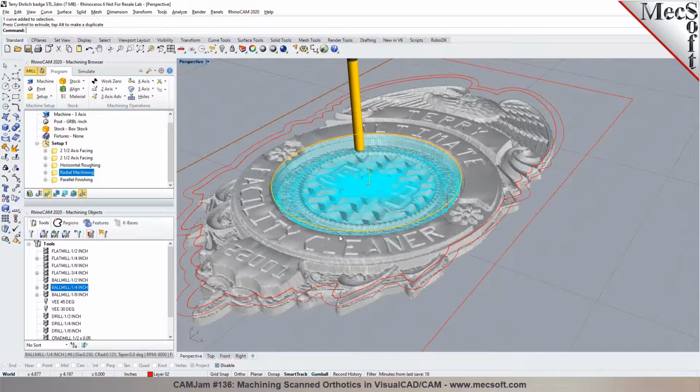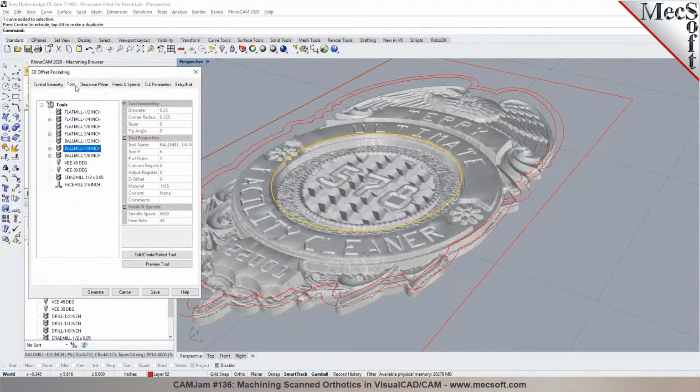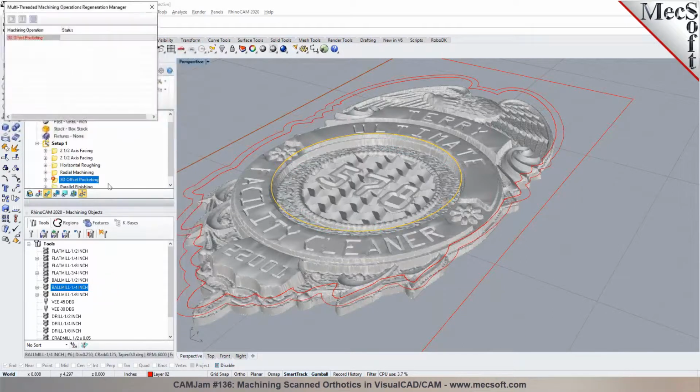With the Pro, we have more advanced 3D methods, like constant 3D step pocketing, which is a uniform 3D step over. It basically uses the curve region that you select to create a uniform 3D offset. The toolpath pattern will be the region that you pick, creating a constant 3D offset. So when I pick generate, this will produce a constant 3D step pocketing toolpath. We also have methods called pencil tracing and remachining to identify bitangencies and scallop and do some cleanup operations.